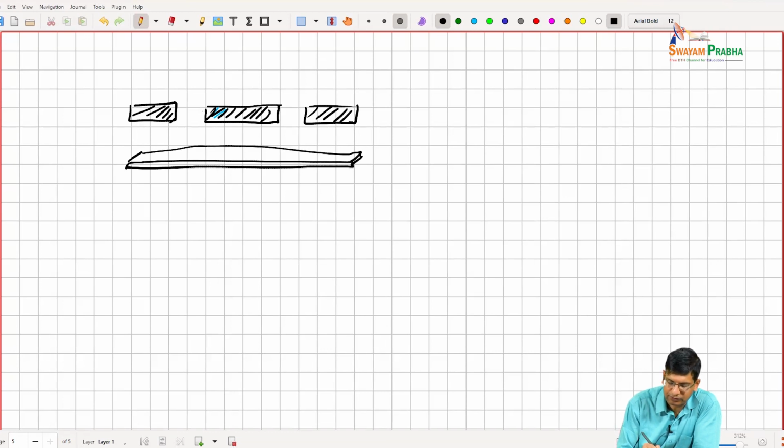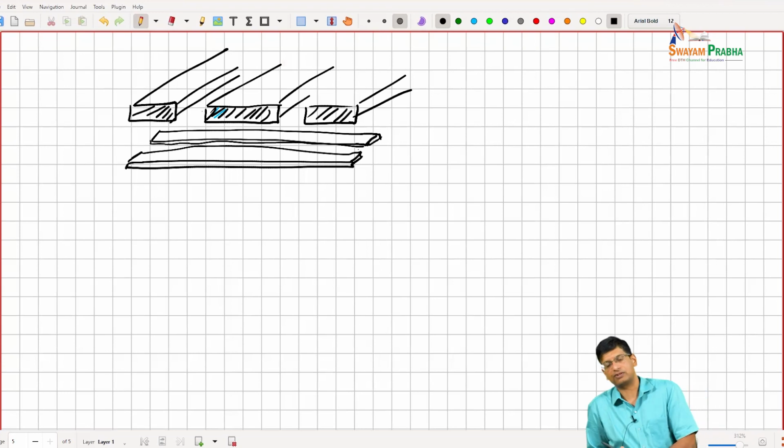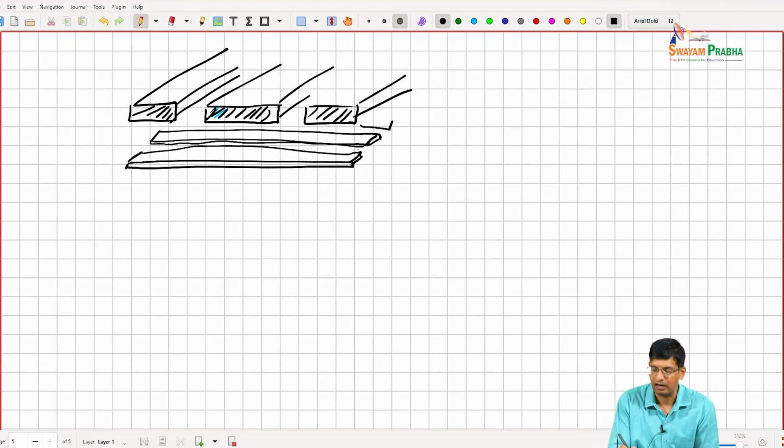So you can place floating strips, you can place grounded strips. They work, but there have been some papers that have suggested that placing floating strips is lower loss, right? But you can basically place these sort of strips underneath your transmission line, right? And using these strips underneath, we are effectively adding capacitances underneath the line in a distributed manner, right?